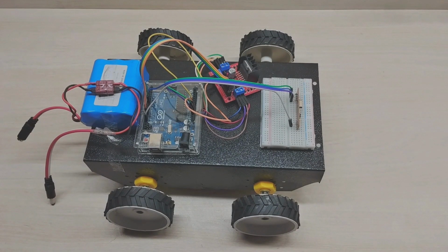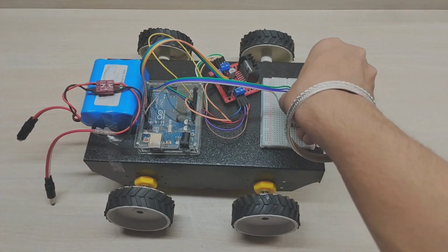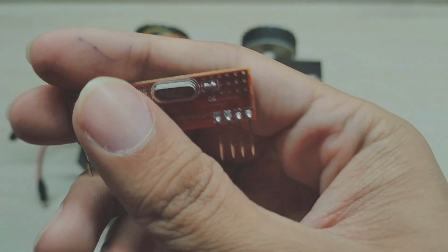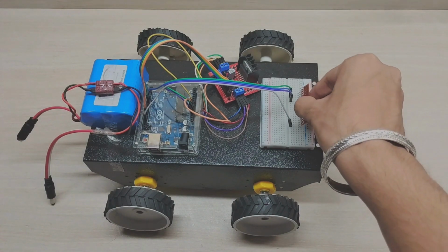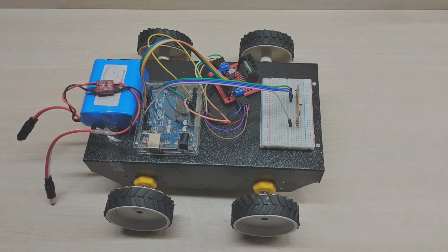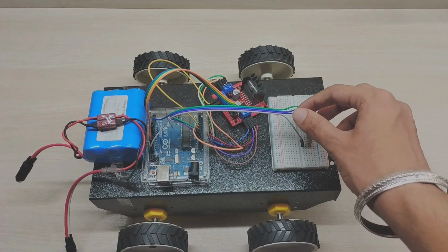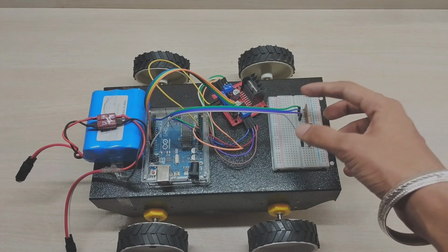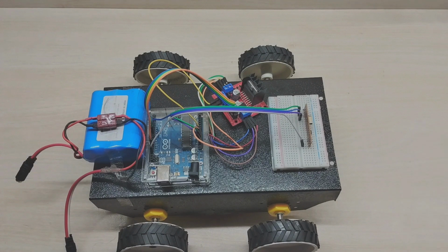Sajpal Singh has explained everything about the master car. Here I, Samrit Mahajan, am going to explain the slave car. Here I connected the receiver which will catch the signal from the transmitter of the master car. This is how the receiver looks. It has a VCC pin, ground pin, and data output pins. I have connected the purple wire to the 3.3V of the Arduino. The blue wire is connected to the third digital pin of the Arduino, and the green and white wires are connected to the ground pin.